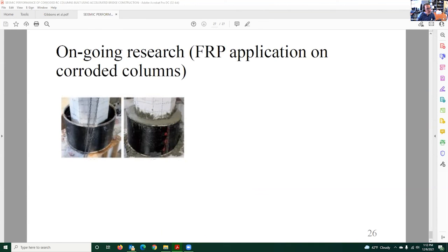He's asking how to incorporate into your model the fact that rebar corrosion is non-uniform inside the concrete. Yeah, that's an excellent question, Xianming. I have thought about it, and what we're going to do, we already started doing it. We will slice the column into finite strips. In the experiment, after the test, we will take out the concrete, measure the bars, cut them, and observe them first.